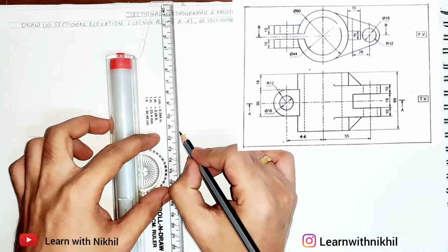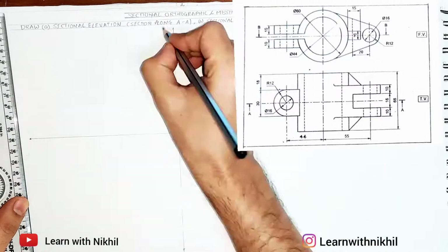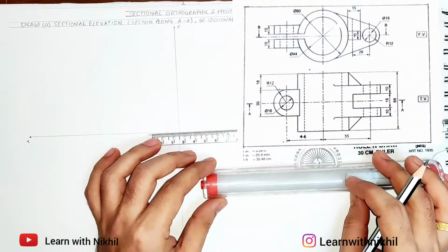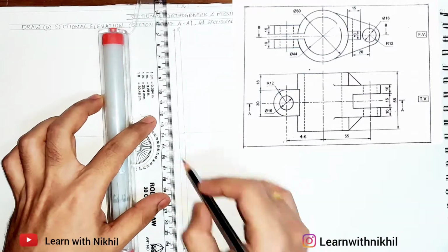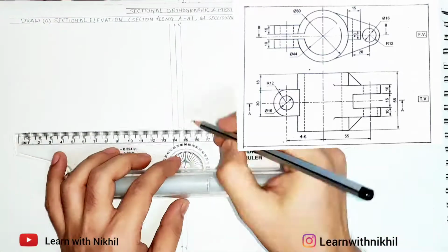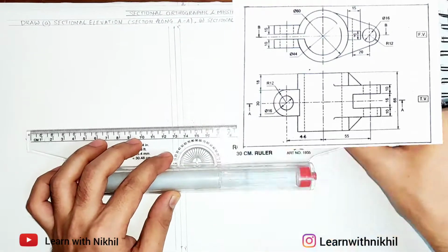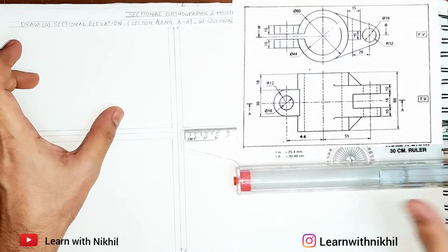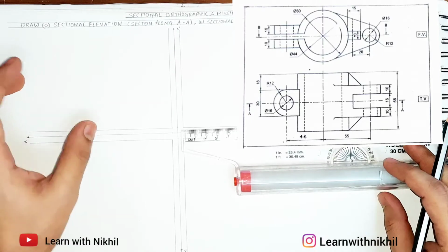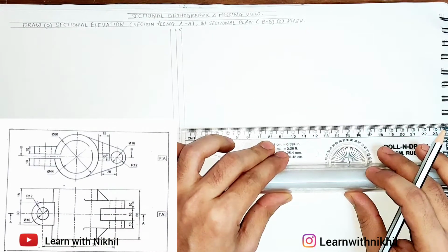So now as we have calculated the height, now we'll draw the axis XY, X dash Y dash, and 5 millimeters apart we'll draw another baseline. Here we'll draw the views. Now as we want to draw the right hand side view, here will be the right hand side view, here will be the front view, and here will be the top view. Now we'll start with the front view.